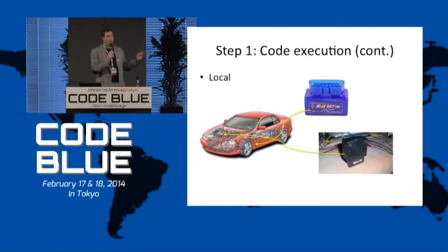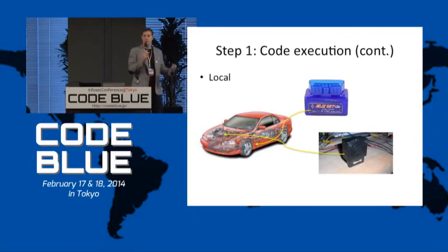There's also intermediaries as well. There's these neat little dongles that people are using to track driving habits. A lot of insurance companies use them. I have this little thing called a Fleet Karma. They mainly are designed to read from the CAN bus over OBD2. That's your diagnostic port in your car. They don't come with the functionality to write.